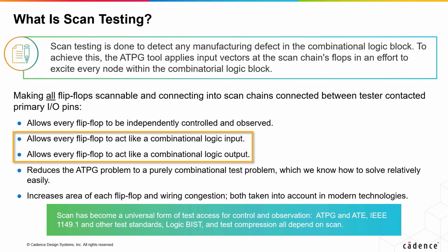In addition, the previous internal state of the chip can be observed at the scan-out pins with a single scan unload. In effect, for test purposes, every flip-flop acts like a chip primary input and primary output. That is, after a scan, each flop is a control point, holding an arbitrary value that can be assigned by the test pattern generator. Then, only the application of a clock is necessary to observe the test results at each storage element, which can then be scanned out.